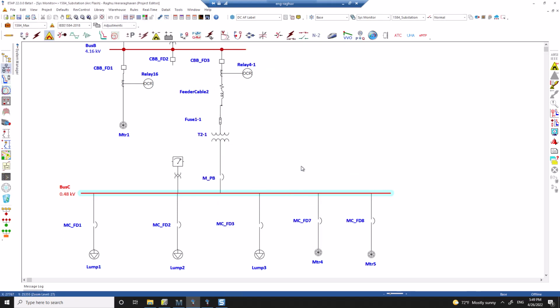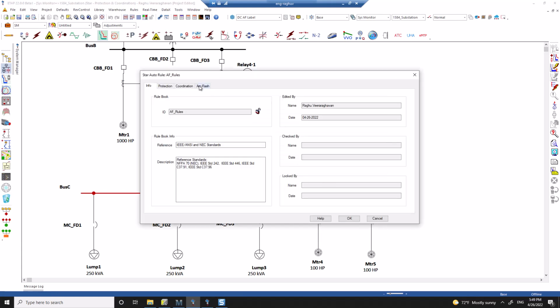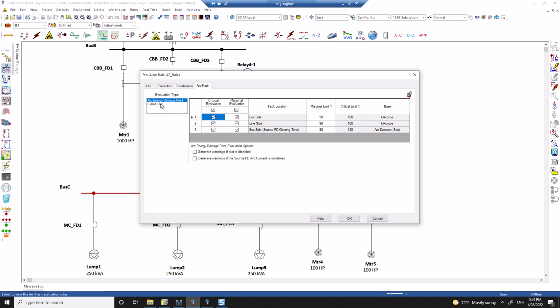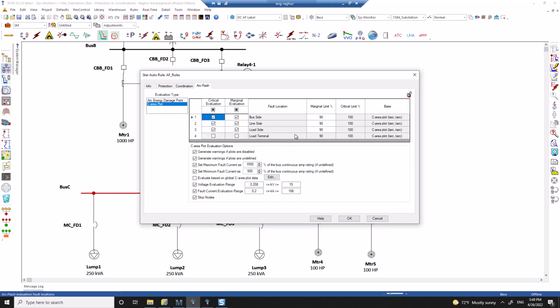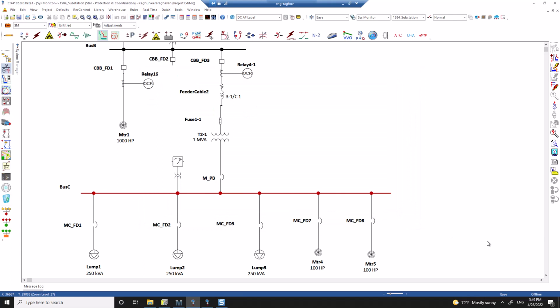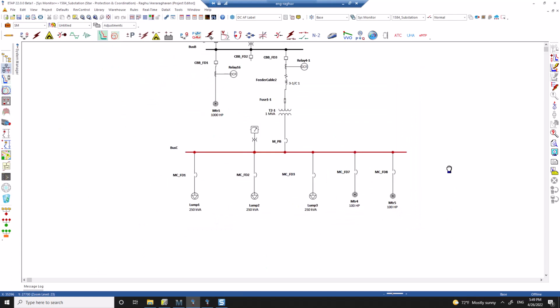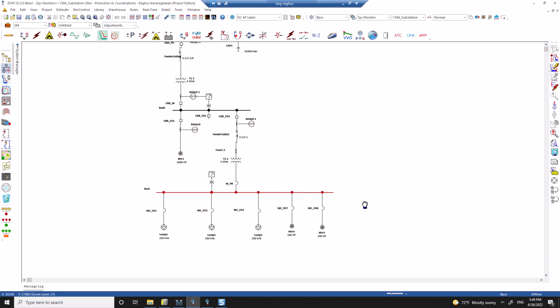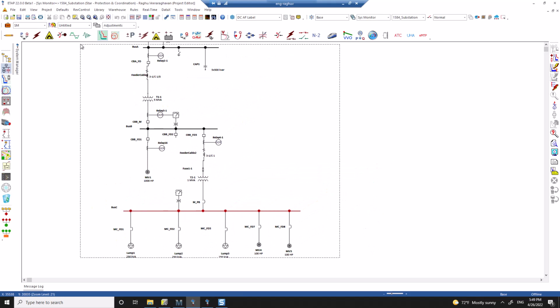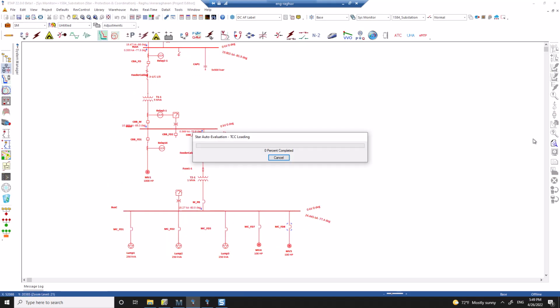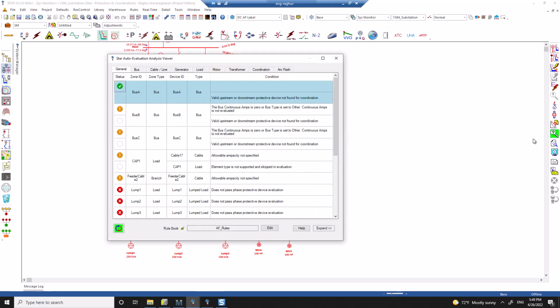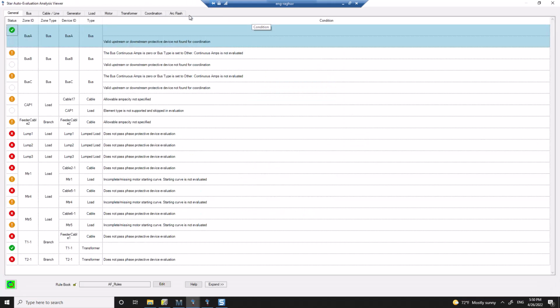So this solution is provided using the Auto ArcFlash module that is available in ETAP, which could be simulated using a common rulebook. Here, you can define the actual rules provided for each incident energy plots, and once this rulebook is shared, a user can simply highlight all the separate locations in one single click and be able to perform an ArcFlash auto evaluation and evaluate the incident energy calculations and the corresponding protection and coordination evaluation in the Star Auto here.